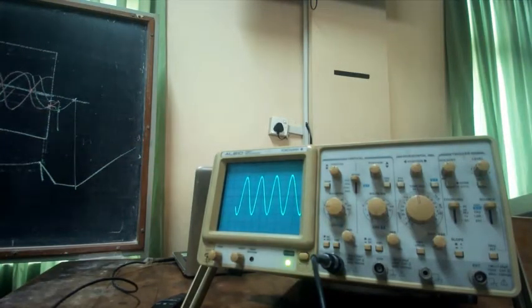This waiting time is basically what is controlled for that. There is a comparator. You will learn this circuit later on in the second year, next semester. But how long do you wait? You compare the signal to the level that I have set. So you have a comparator, and this is the level setting, with plus and minus voltages, and then this is the signal itself.